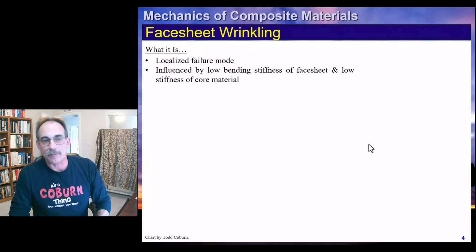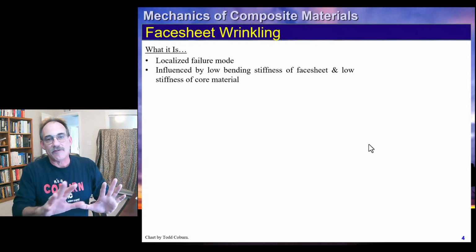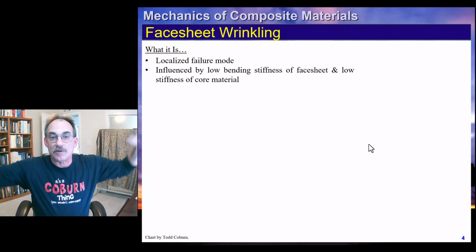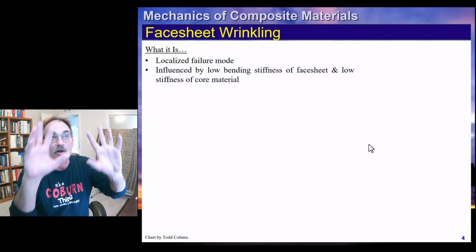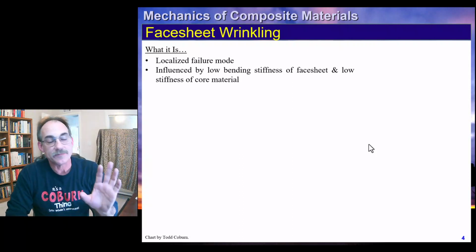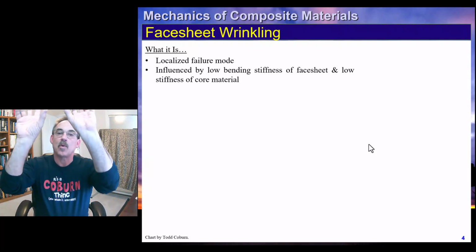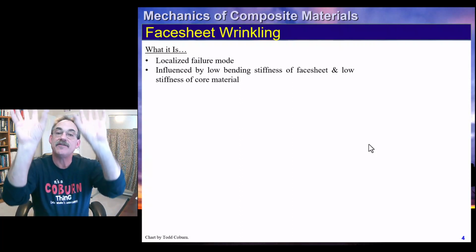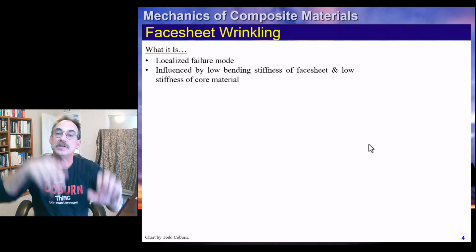It's like crowd surfing. Imagine the face sheet hurls itself on the crowd of the core material, and all the core material is just carrying it up with its little fingers. And if any of the little core material has got a low stiffness, then the face sheet can buckle down into there.